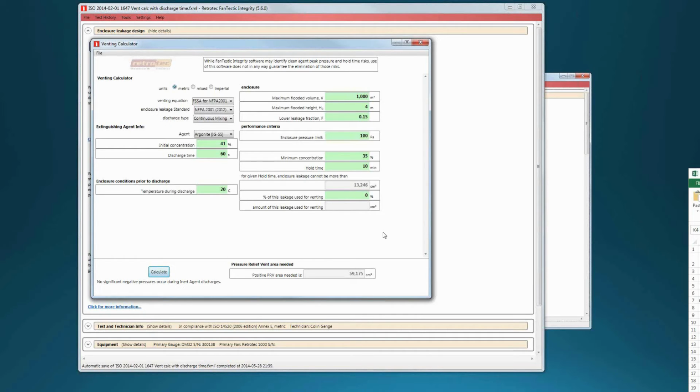Okay, that's fine, but that means that we're going to have an absolutely massive peak pressure, because it's going to require that the enclosure have a lot of leakage in order to keep the peak pressure down to this limit. So no matter how many tricks we pull out of our bag, we can never get the enclosure leakage to a high enough value here that we can get around using pressure relief vents.